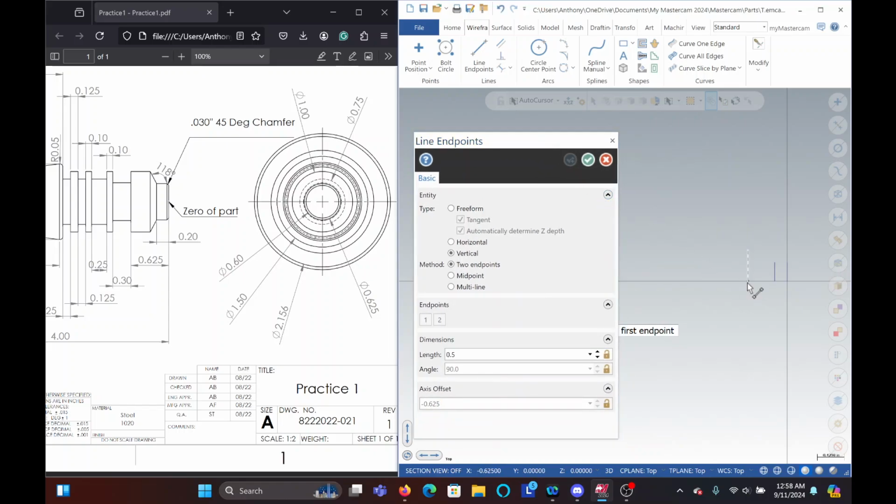So the next one is the actual trick. So I'm going to start where I ended this one. My length is going to be 0.65 divided by 2, which is going to be the half of the diameter right here, 0.625 here, and it's going to be minus 0.3 at the very bottom. So basically you're subtracting this to get your next point.